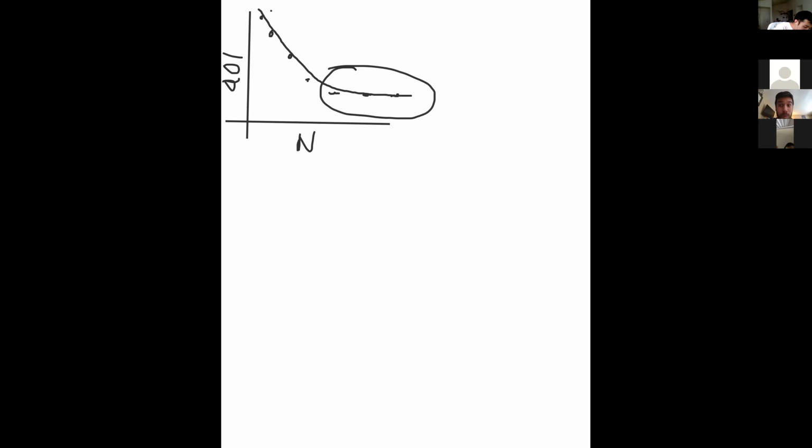Okay. So in the last graph, I showed you that the quantity of interest was increasing as we increase the mesh, but it can come from the opposite direction too, right? So you could very easily have a condition which looks like this. Like before, the x-axis is n, the number of elements, and the y-axis is your QoI. So it can really come from any direction, either above or below. The only thing that matters is this part right here, which is you want to see that your quantity of interest will plateau.